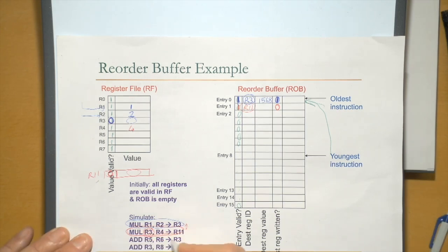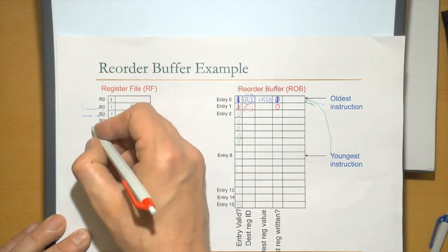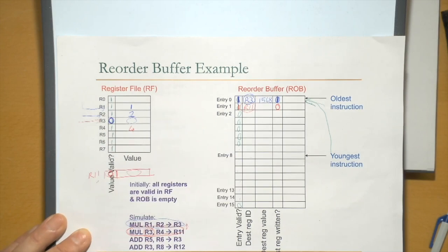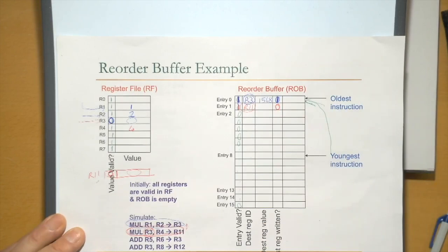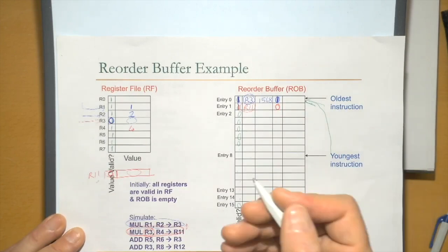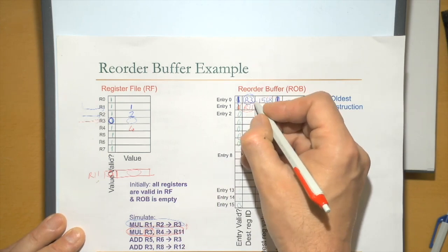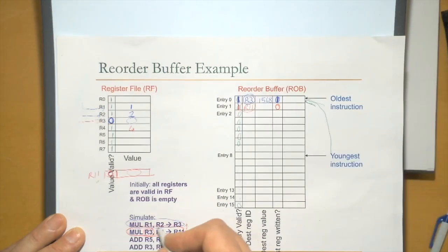Now let's redecode this multiply instruction in this new scenario. If we redecode this multiply instruction, what we do is we check R3. Is it here? It's not here. Now, if you want to check whether it's somewhere here, what do we need to do? Well, we need to basically look for whether an R3 exists earlier than this instruction, somewhere in the reorder buffer.